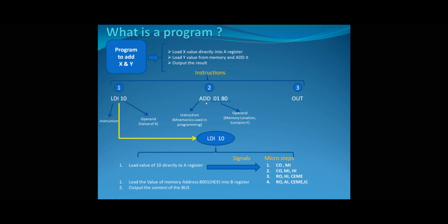However, some of the instructions, like instructions that point to a memory address, such as the add instruction, are going to have a 2 byte operand. That means we have two 8-bit values back to back at the next memory address that need to be processed by our logic.